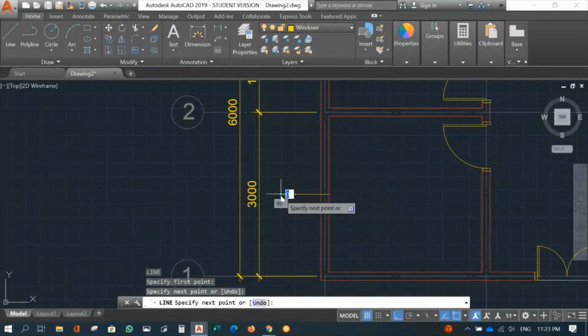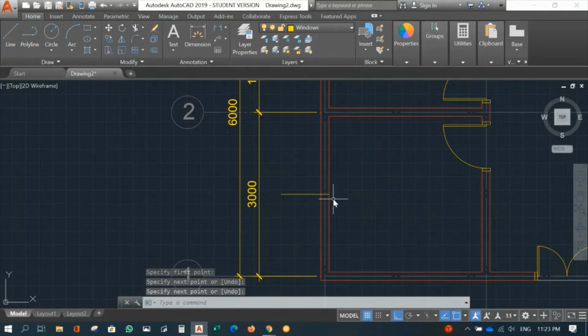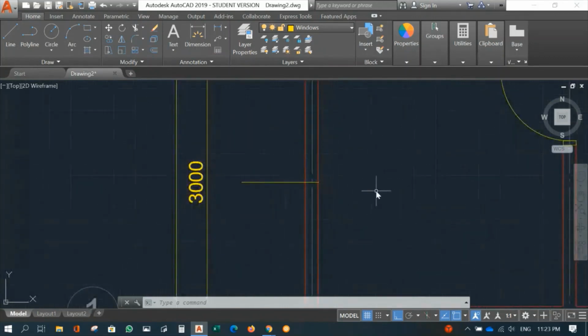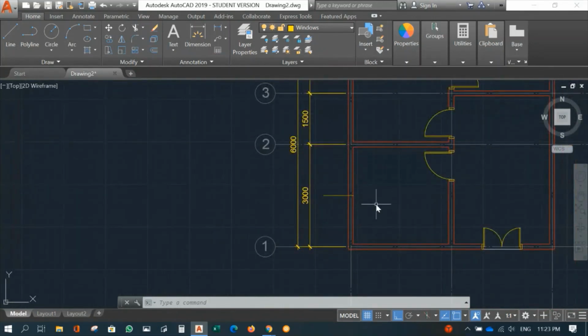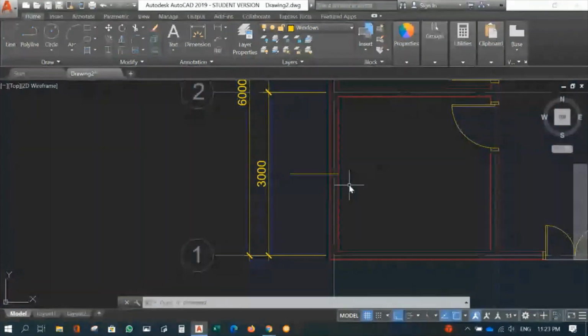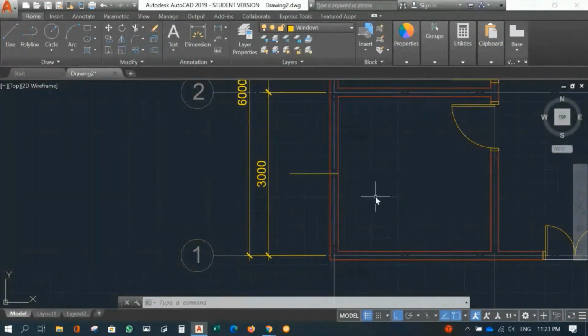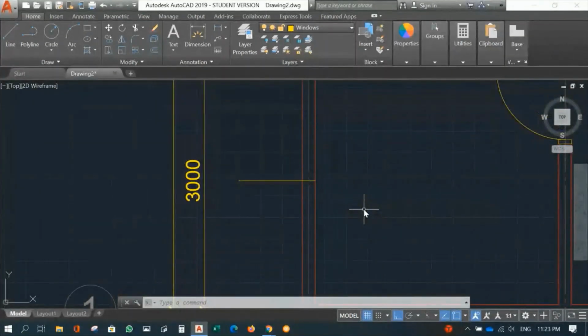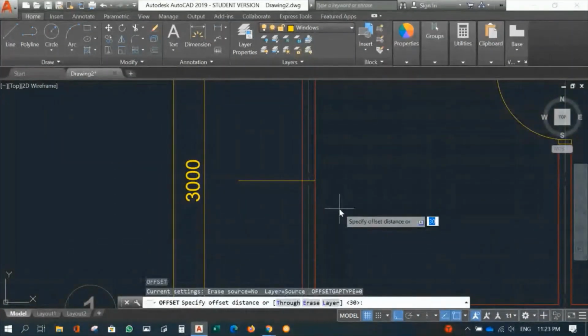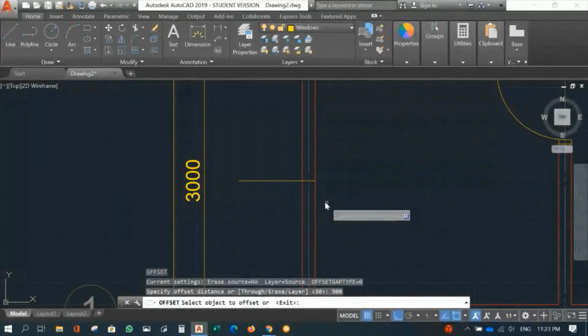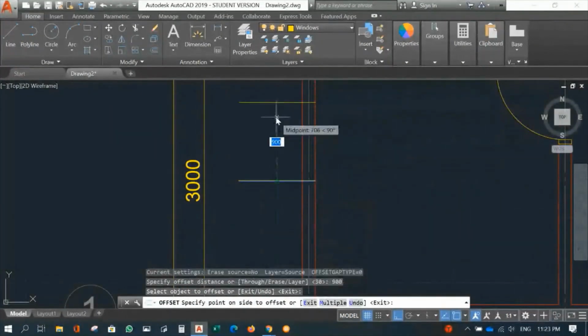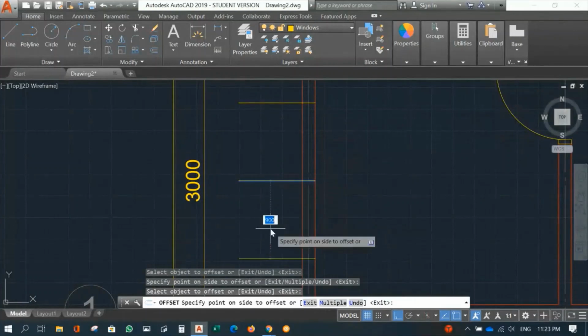Why this is important is because if we take the middle line here, it means that the window will be set up nicely in the middle of the space of the wall here. Right. So I'm just going to use a 2 tiers window, much easier. Okay, so I'm going to offset this window here to 900 to the top and to the bottom.